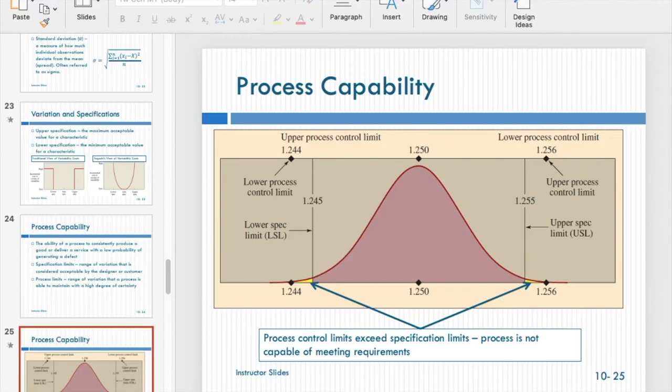You can tell your employee that we hope the length of the product is 1.25, but you can have, let's say, 0.005 error in both directions. What does having an error of 0.005 in both directions mean?